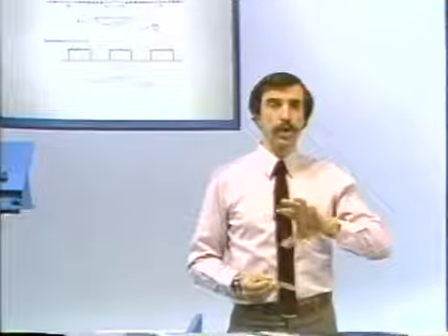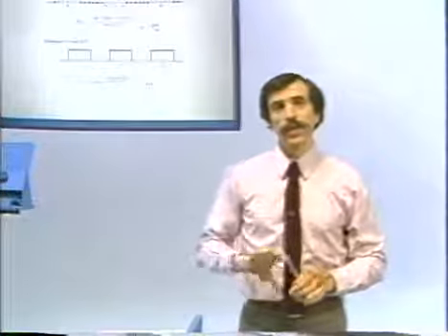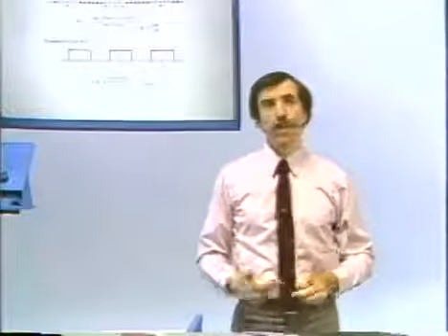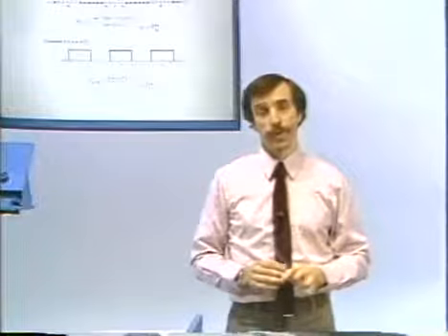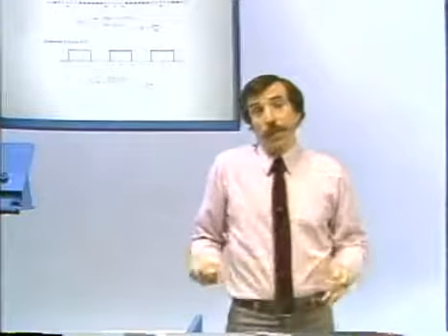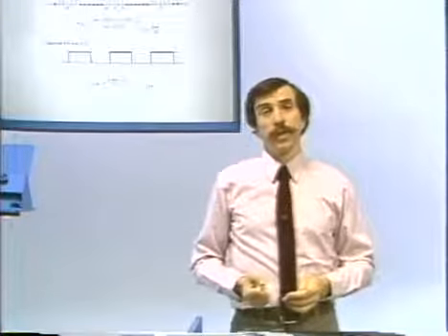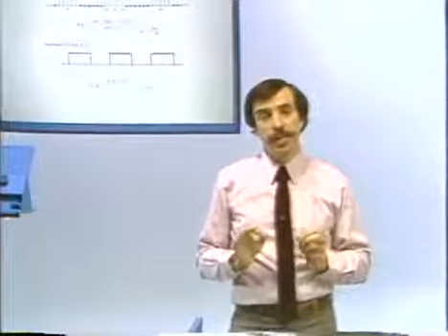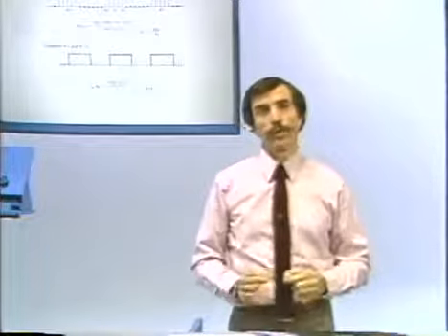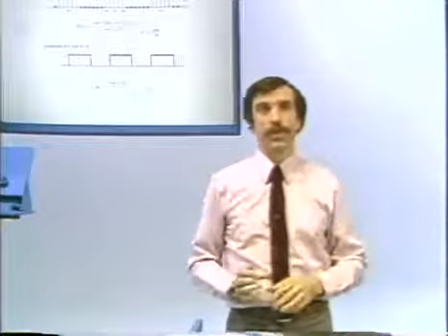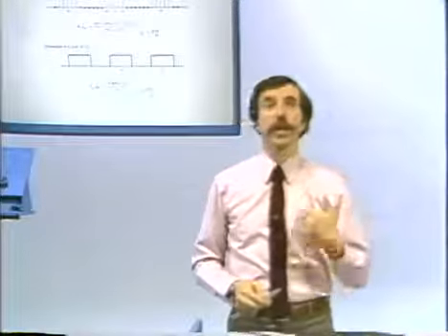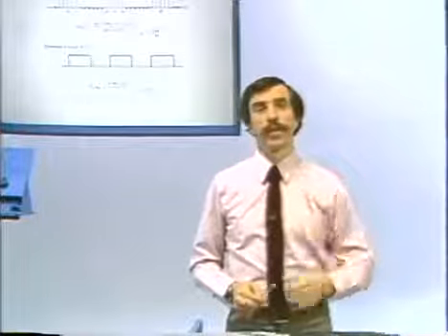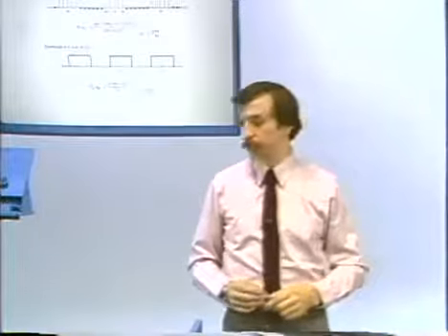And in fact, we should understand right from the beginning that the sine x over x envelope couldn't possibly be the envelope of the discrete time Fourier series coefficients. One obvious reason is that it is not periodic. What we require, from the discussion I've just gone through, is periodicity of the coefficients, and consequently also periodicity of the envelope in the discrete time case.